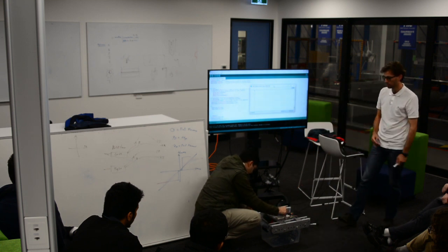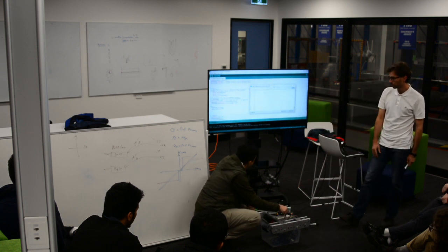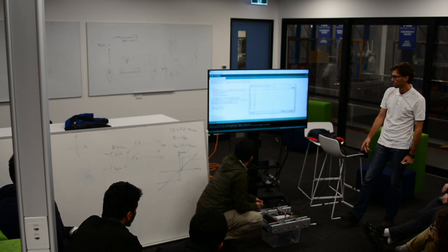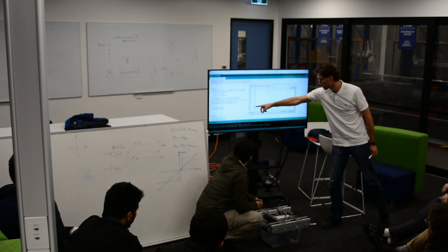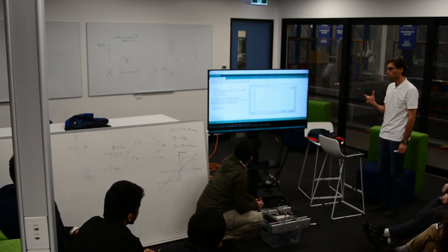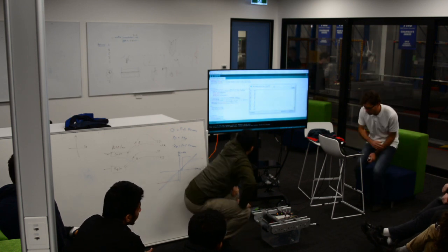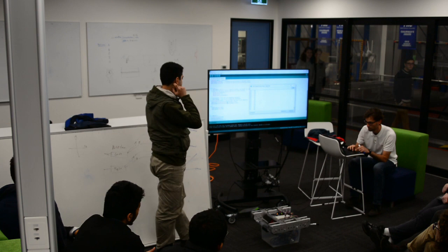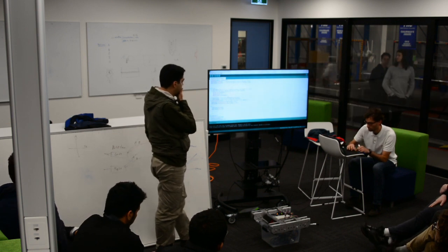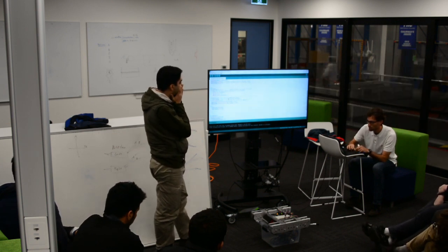So we're going to do that by increasing our gain again. So let's go up to 0.6. So this is how you tune the P. And in a full PID controller, you still tune each value independently through a sequence of slowly increasing until something happens, and then you go to the next one and you increase, and then you do the next one and you increase. Okay, let's see, how's our serial monitor?